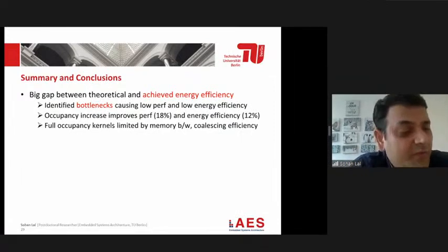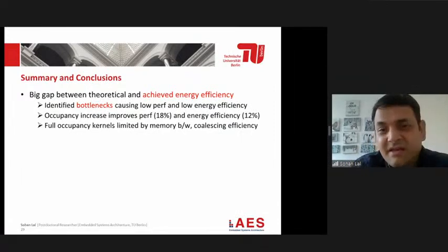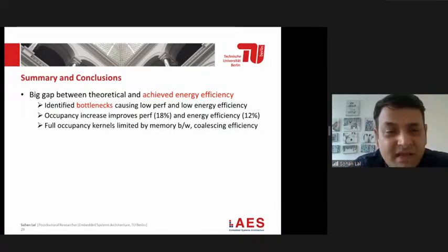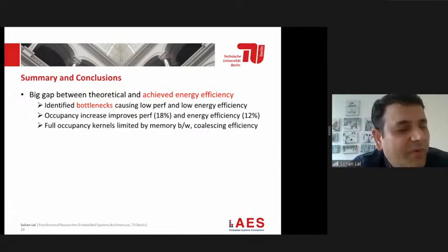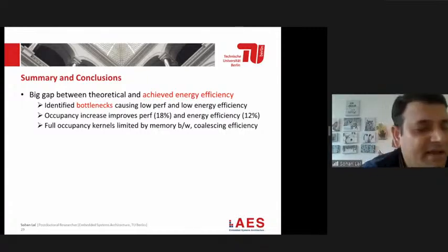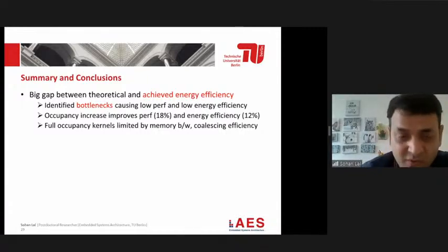We figured out if we increase the occupancy, it can increase the performance and energy efficiency. On an average, let's say 18% and 12%. But we also figured out that just increasing the occupancy is not enough. For the full occupancy kernels, we show that they might be limited by memory bandwidth, coalescing efficiency, or SIMD utilization.